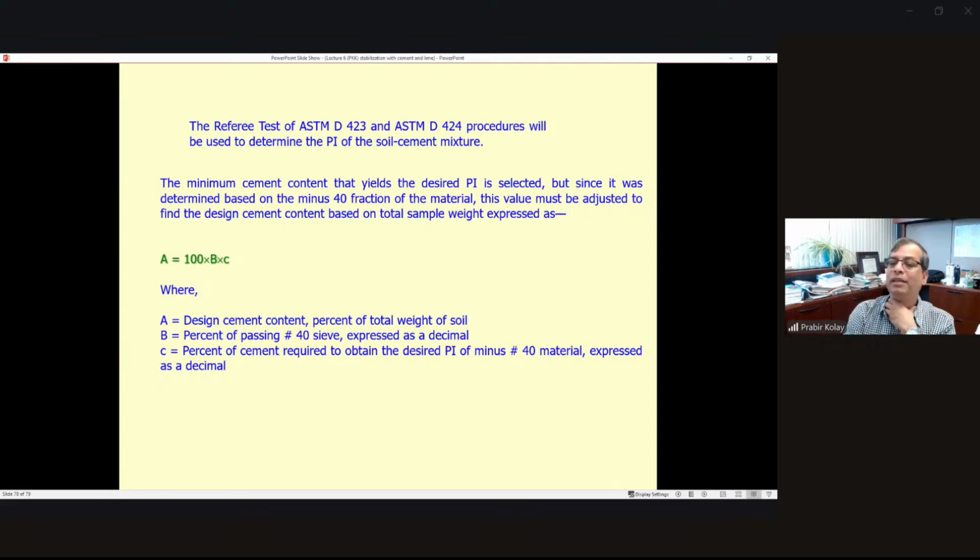Yeah, if it is expansive soil, and you use lime, obviously lime will increase the strength. So again, what type of test you're going to do? If you do the expansion index test or any other test, first, as I mentioned, the density, as I've seen in the standard Proctor graph, the lime is going to decrease the maximum dry density, and the optimum moisture content is basically increased. But when you prepare the soil sample, with time, it will be fine.